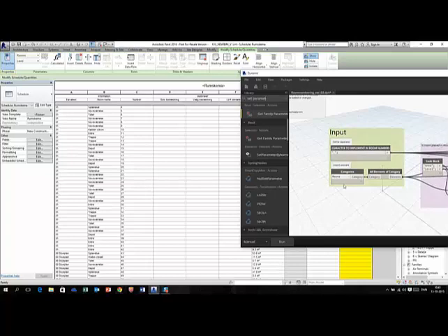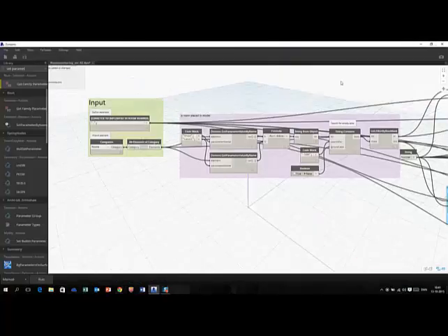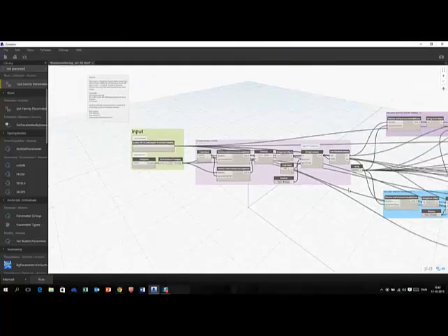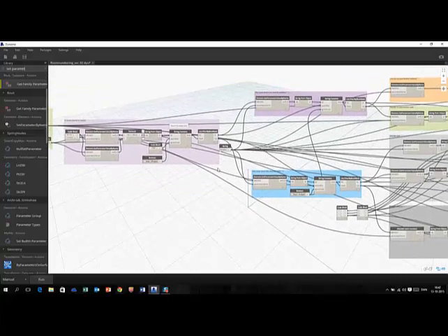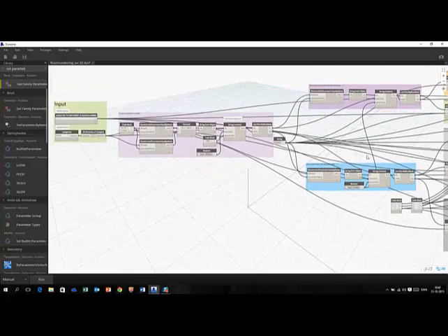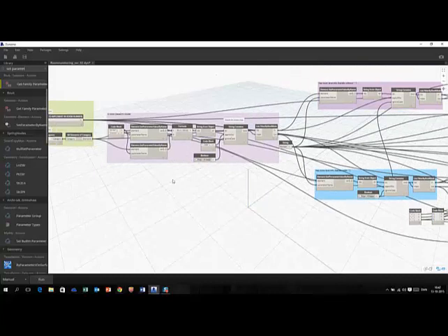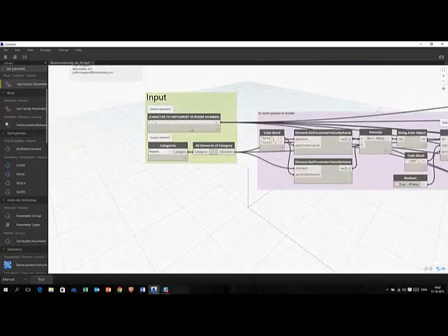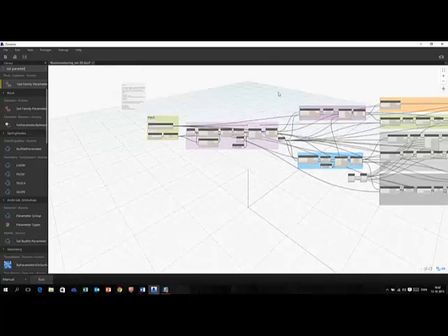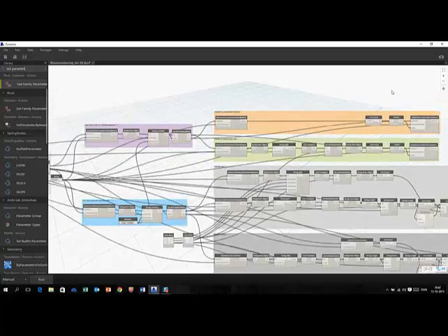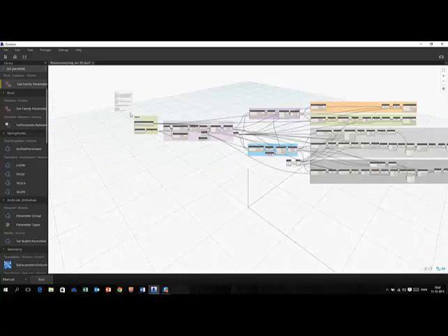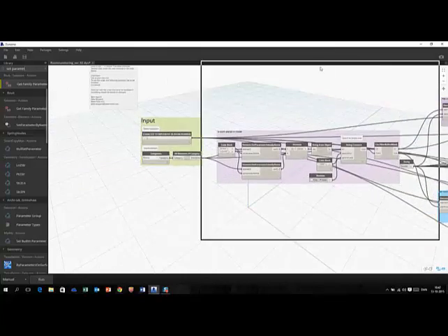So what it does here is that it's looking in the category of the rooms and then seeing in Dynamo, in Revit, is the room itself placed? Is it a placeholder design? Does it already have a reference to the dot that I have put in as a separator between the level name and the room number? And does it have any intersection, or is there somebody giving a fake level number? So all these things Dynamo would control for me.